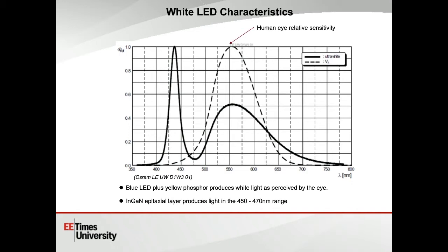And so the first blue LEDs that came out weren't actually LEDs at all, but small incandescent bulbs surrounded by a blue diffuser to give a blue output. The first semiconductor devices used silicon carbide substrate, but they were very poor in terms of efficiency. Successive generations of devices improved the efficiency tremendously by switching to gallium nitride as the substrate. The first high brightness blue LED didn't come around until 1994. And this was such a major breakthrough that 3 Japanese scientists won the Nobel Prize for Physics in 2014 for developing it.